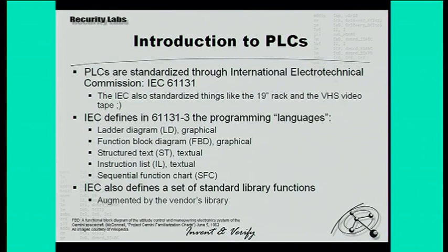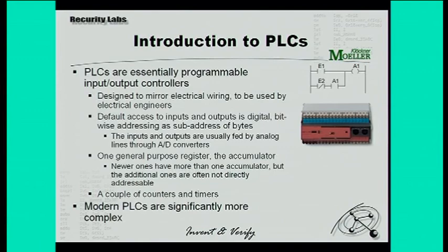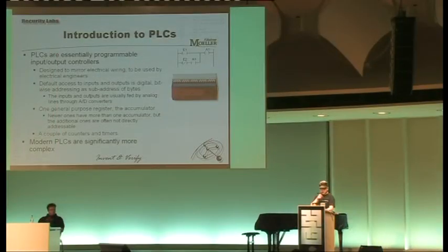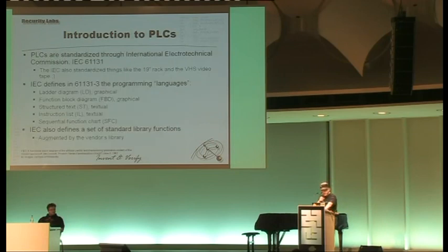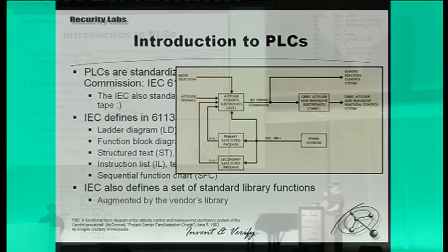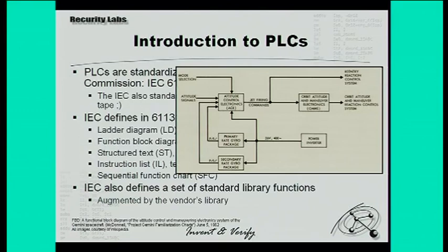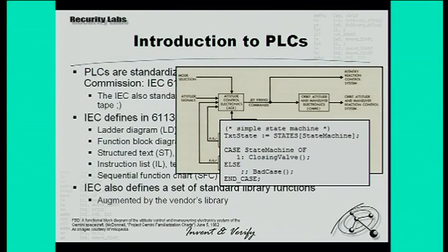The first one is the most commonly known, ladder diagram. That's what you see up here. It actually looks like an electrical engineering wire-up painting. Then there's the function block diagram. This is from Wikipedia. This is actually part of the Gemini project from NASA. They somehow gave it to Wikipedia for whatever reason. To the English one, of course. The Germans deleted it. Then you have a structured text representation that you can write in that pretty much looks like Pascal with all its beauty.